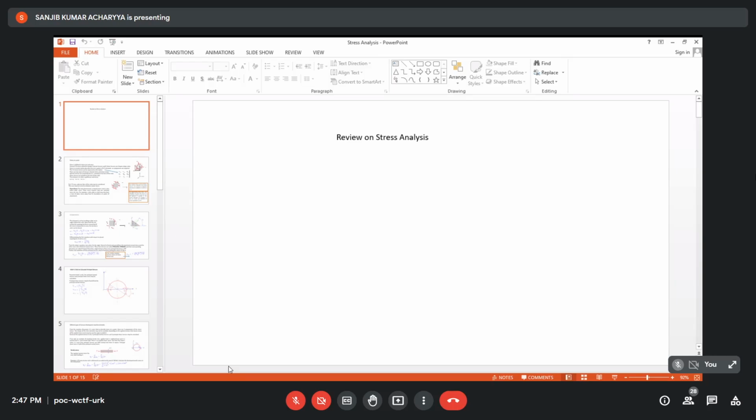Yes, sir. Clear, sir. And after knowing the stress, the designer has another inquiry. What is the limit of that stress that a material can sustain without failure? So that is another material testing part, material property part. And if a designer knows this material property, either consulting from a catalog or directly experimenting in his own lab, then he knows the limit of stress which can be allowed for this particular material.